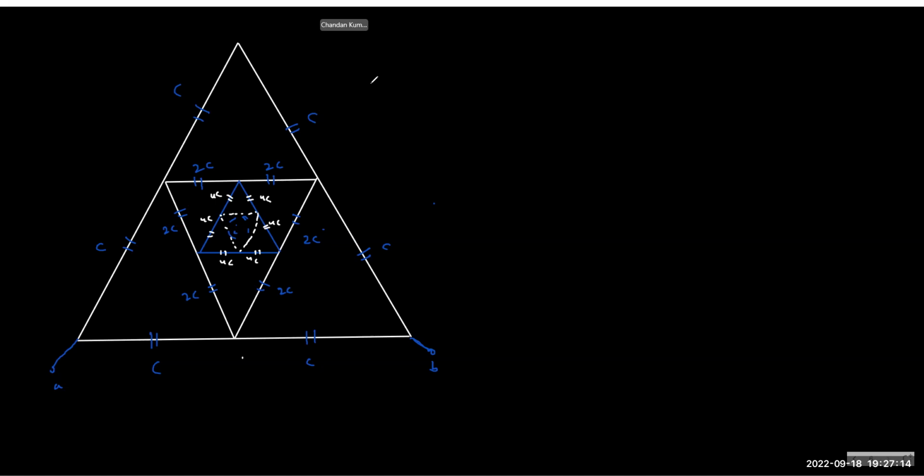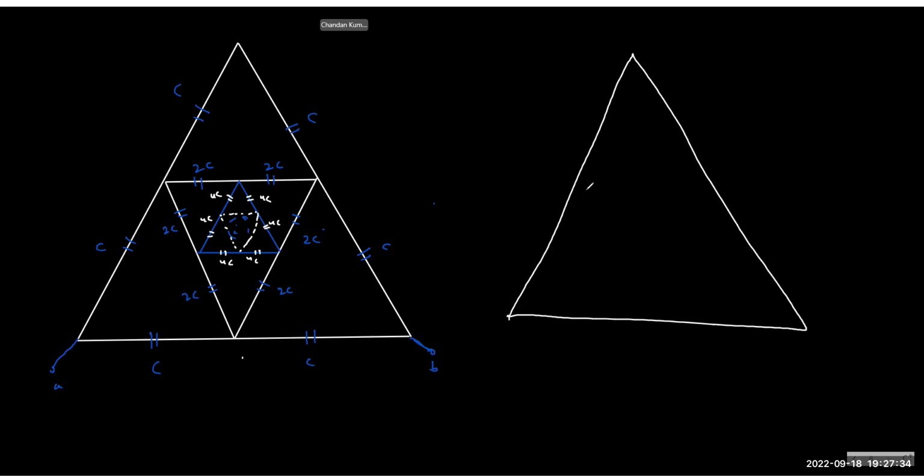And if you look carefully, every junction which is lying on the line of symmetry will have a disjoint connection. So you can remove it. Although it looks like touching, you can remove it. So in reality, it will look like a big one, but this branch will be removed here. It is not touching because it's disjoint. But for this branch, this is not touching, so it is disjoint. This is disjoint, and so on.